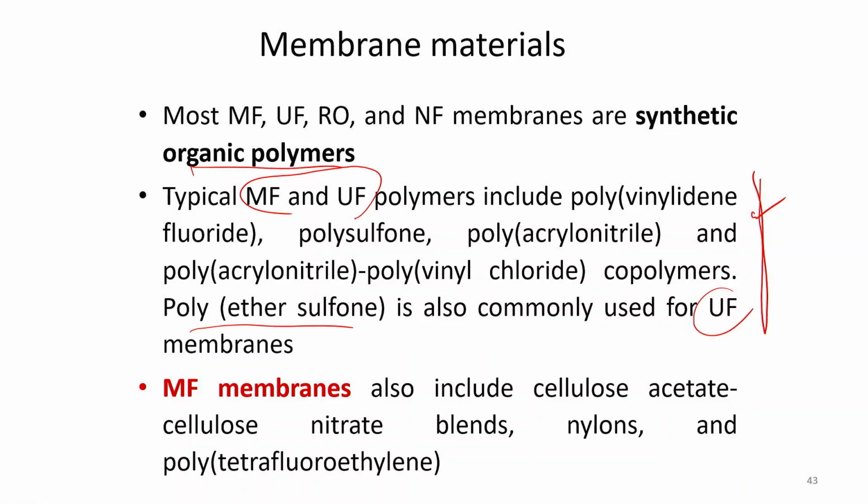And for microfilter membranes, we can also use cellulose acetate, okay, and a cellulose nitrate blend. We can use nylon, different types of nylon. We can use PTFE, polytetrafluoroethylene, for microfilters. PTFE membrane is very commonly used for microfilter membranes.